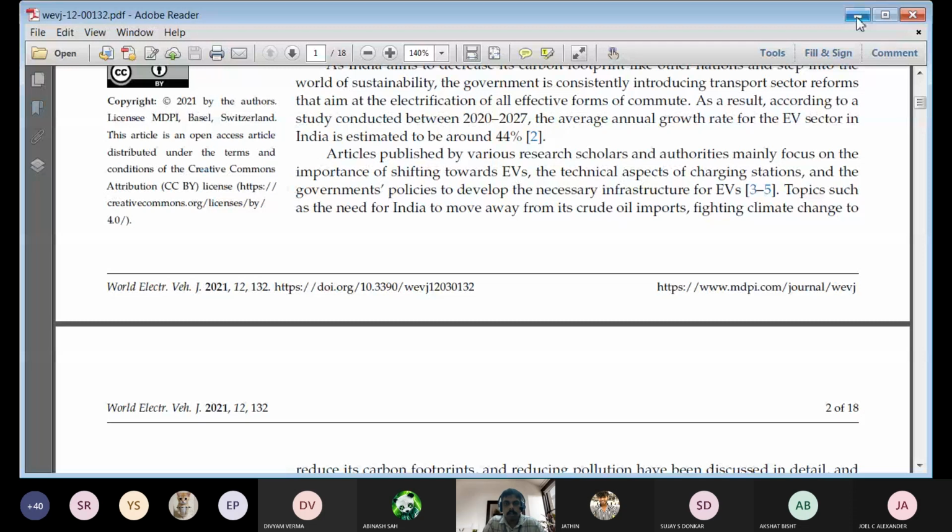So this is the usual sensor, the thermopile. We want the voltage only, so we can use another sensor. Even a photovoltaic cell we can use, but it has some demerits. It won't capture the whole spectrum of solar radiation. So people are not preferring solar cells.